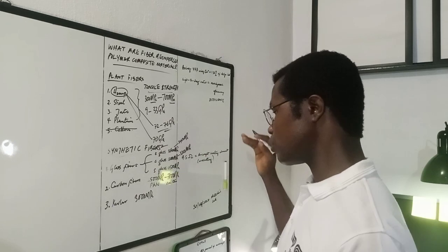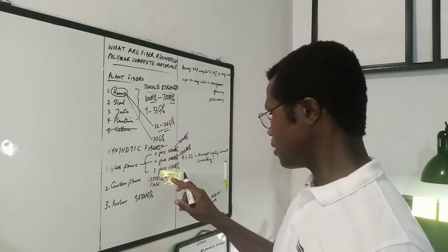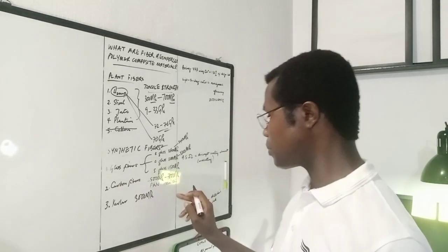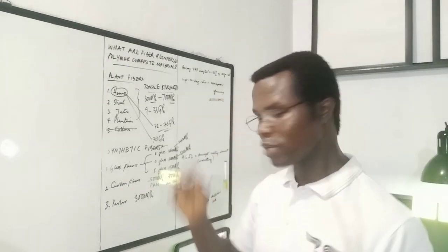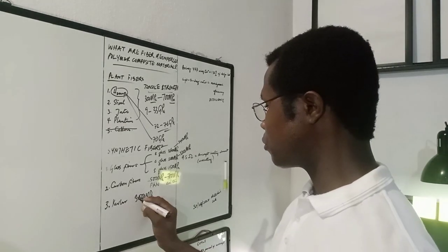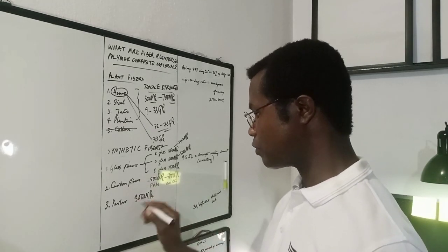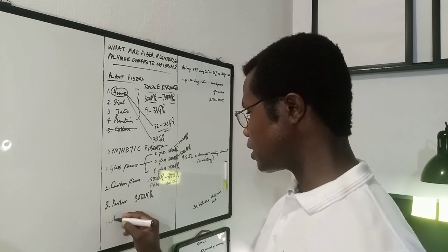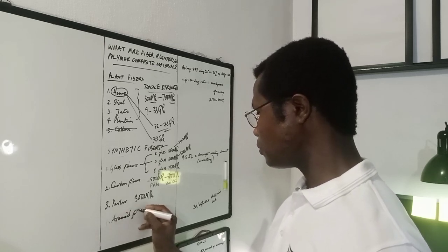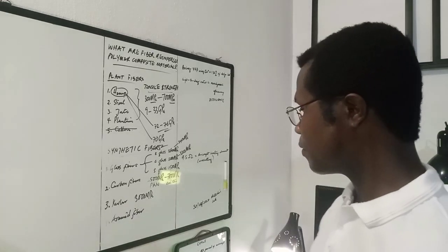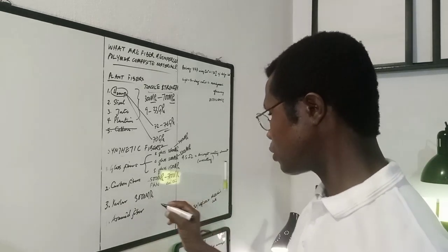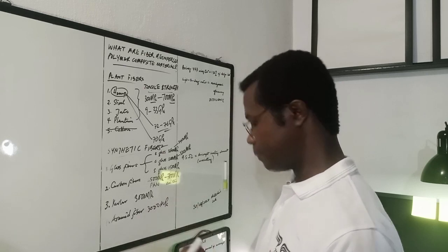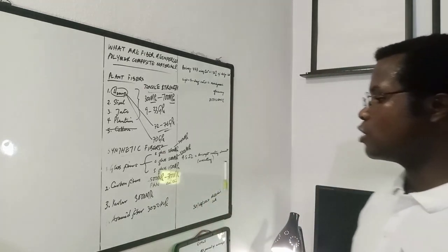The S-glass edges out the average. The carbon fiber made with the coal tar precursor accounts for the highest end of the spectrum so far. For aramid fibers, which are another type of synthetic fiber, you have a similar result, also in that same range of 3,000 megapascals. Very close in that range.